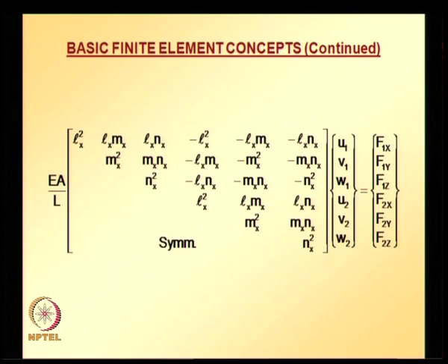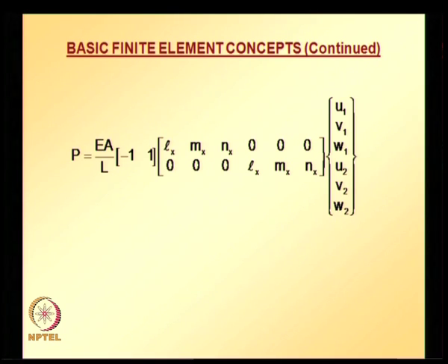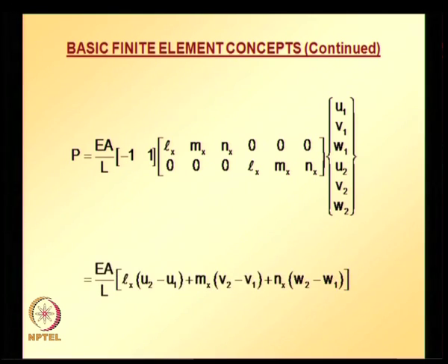Axial forces can be computed by transforming displacements back to the local element coordinate system. So once we get the global displacements, we can calculate local displacements. Once we get local displacements, we can calculate strains and then stresses, and using those values we can calculate the forces in a 3D truss element. The equation is given here, and this equation in terms of direction cosines after manipulating the first equation is shown there.